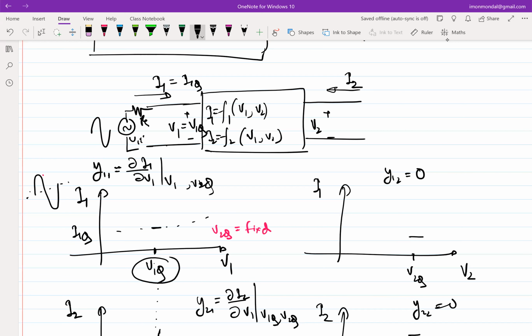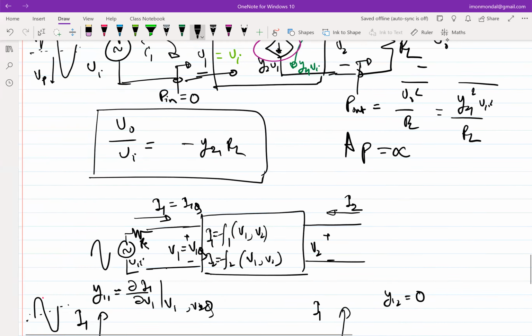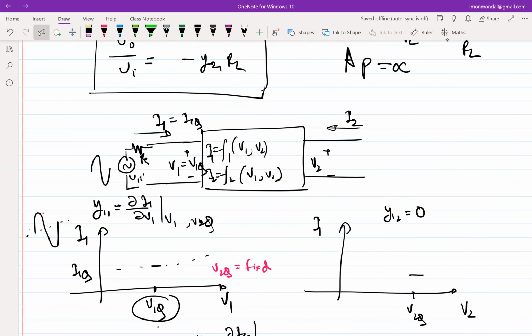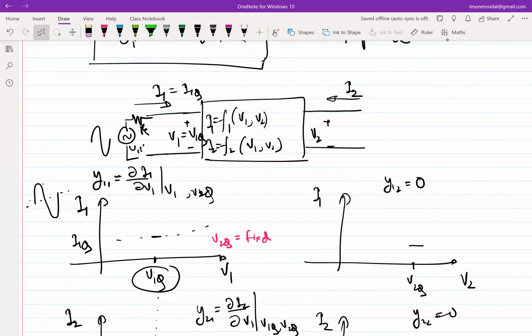So naturally, we are expecting from the incremental model of the transistor also, the input VI should arrive completely at the input port. In the total picture, where I'm trying to draw a conclusion of what is happening to the total voltage, this essentially means that that incremental VI is riding on top of some quiescent voltage, right?